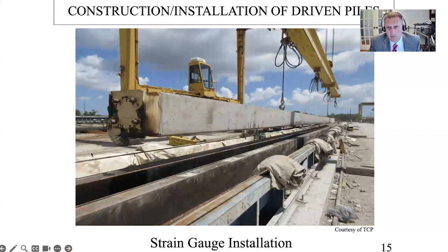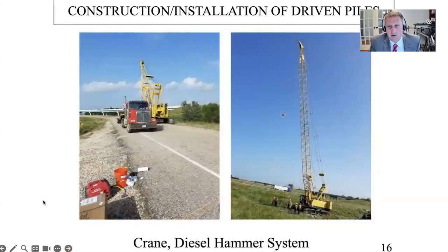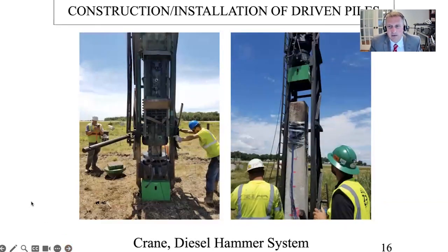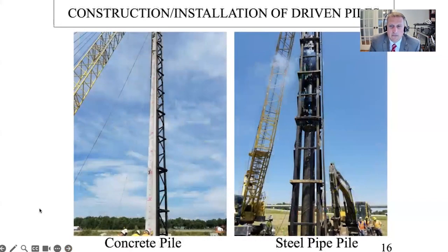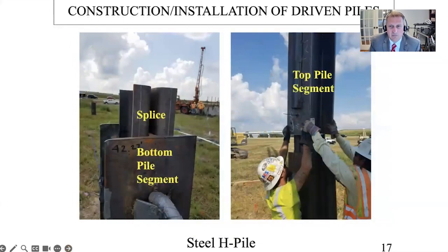So here are those piles coming out of the pre-stressing bed, and they were hauled to site. We had volunteer work done. This is Chris Hill Construction out of Memphis that did the pile driving for us, just using a typical diesel hammer to drive these piles, and all of the piles were driven with the same hammer. Swinging set of leads there.